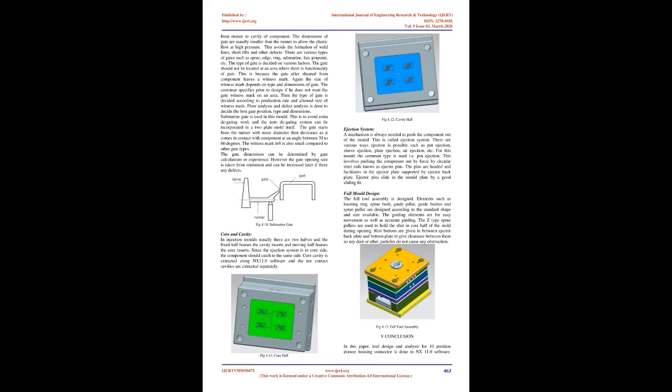It is important to extract the main insert and 10 contacts inserts separately. This is due to high production and accuracy. The contact inserts are manufactured separately, precision fitted with shoulders and main inserts. These cavity inserts are present on both cavity and core sides. The contact inserts have critical dimensions, and if in case they break or wear out, only the particular insert can be changed easily instead of changing the whole insert.